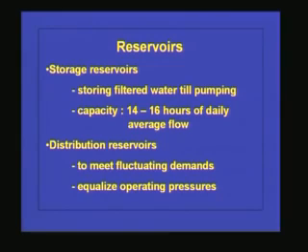We may operate the distribution network only for a few hours, but you need to store the water to meet the demand for 24 hours a day. So the capacity of the storage tank is normally taken as about 14 to 16 hours of daily average flow.